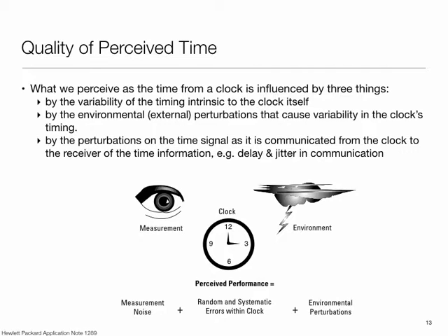Now, if you're dealing with applications with tens of milliseconds type requirements, all of this is fine. On the other hand, if you're measuring the time of flight of a signal between two nodes, then you are seeking nanoseconds or microsecond type delays, and then things become problematic. So in many applications, you have to start dealing with timers right at the hardware level.